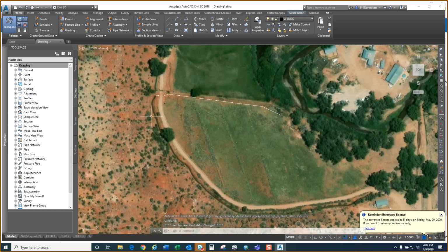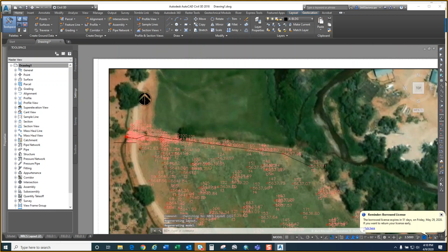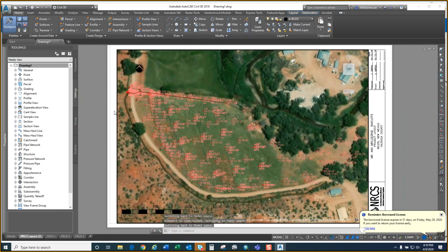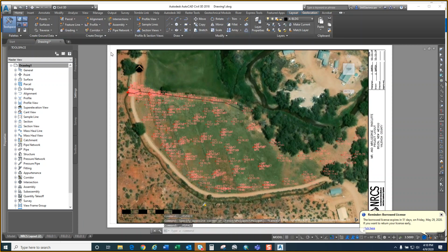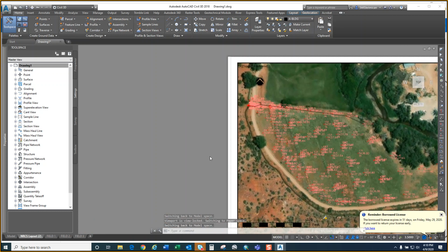At this point, before I go, now I have enough for the pipeline, so I'm going to get out of model space and go back into paper space. There's my draw. I'm still in model space because the viewport is highlighted. If you double click, now I'm in paper space. But I want to be in model space, even though outside of model space, this is all paper space.